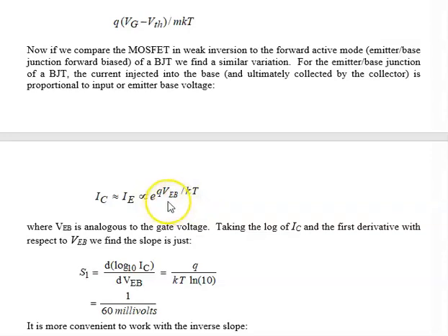This is for a PNP. So for a PNP, the emitter is at a higher potential than the base, because P for the emitter, we put a positive potential on the emitter, which forces the depletion region to be smaller. Positive will push, not pull, but push holes from the emitter into the base.